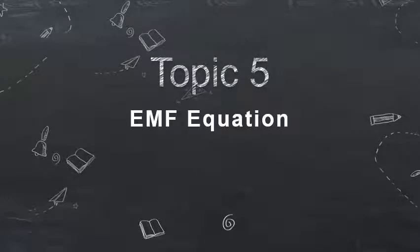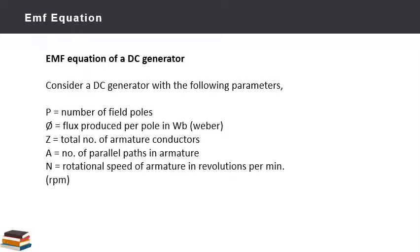The next topic is the EMF equation, or electromotive force equation. So, EMF equation of the DC generator. We consider a DC generator with the following parameters, where P is equal to the number of field poles, phi is equal to the flux produced per pole in Weber, Z is equal to the total number of armature conductors, A is equal to the number of parallel paths in the armature, N is equal to the rotational speed of the armature in RPM, revolutions per minute.